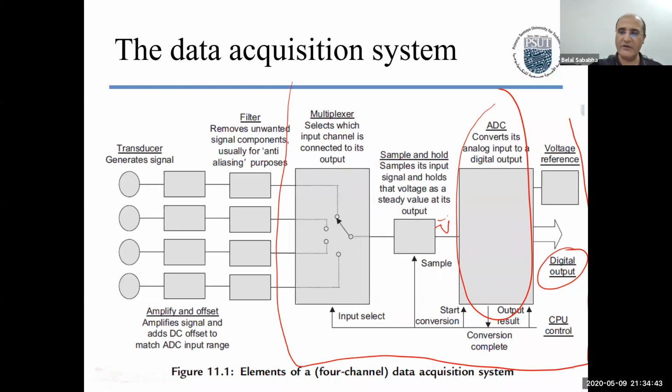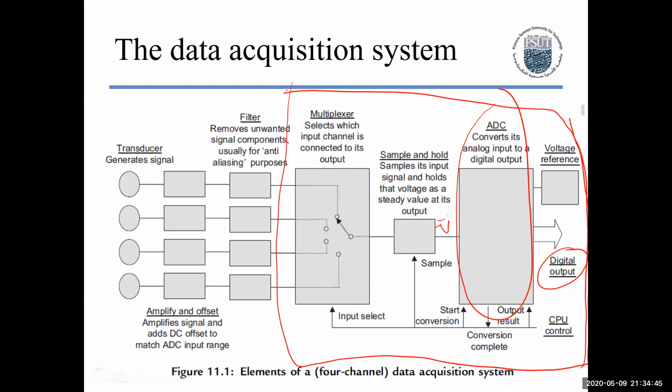See this square? Millivolt. Which one has less error, 5 millivolts or 20? 5, right? More precise because it has less error. Yes, it's more precise. It has higher precision, right? Instead of telling me that the temperature is either 1 Celsius or 2 Celsius, you can tell me it's 1.25 Celsius or 1.5 Celsius. You have more precision.